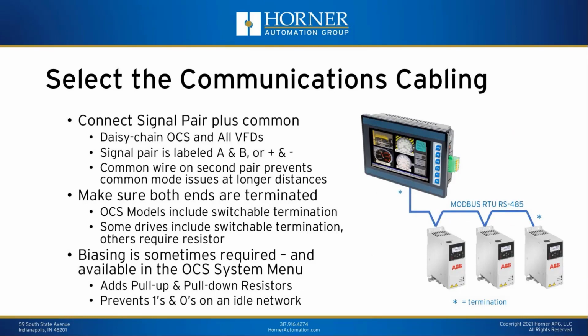Okay, now once we've selected the actual field bus or communications connection, we've got to get the cabling right. All these details you see here on the screen are about the cabling details for Modbus RTU over RS-485, which is far and away the most common electrical interface between a PLC or an OCS in this case and variable frequency drives.